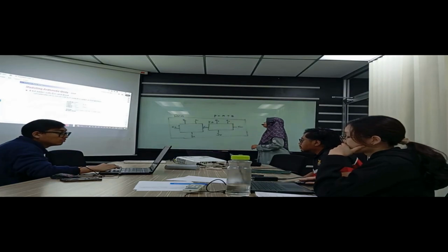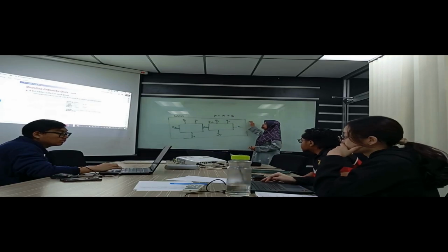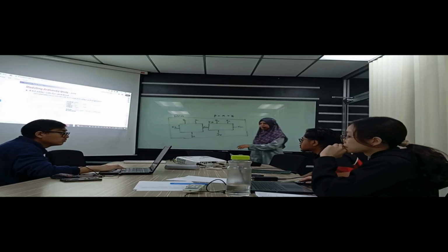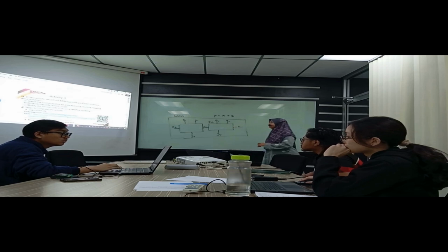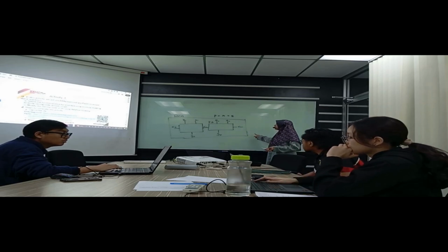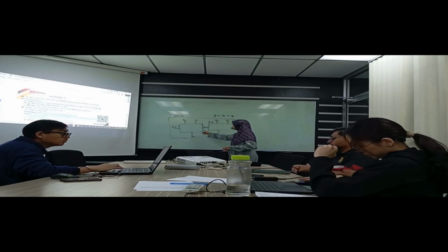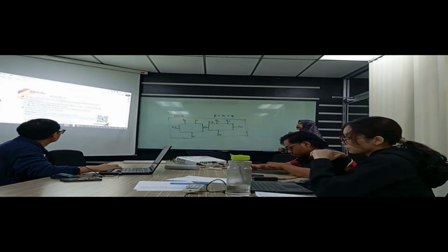How do we model this arithmetic, this adder or this RCA, in Verilog code? Let's see through activity 3. First, you have to sketch the functional block. Let's say for a 4-bit RCA, but what I did now is for 2 bits. So you need to expand another 2 blocks to get the 4-bit RCA.